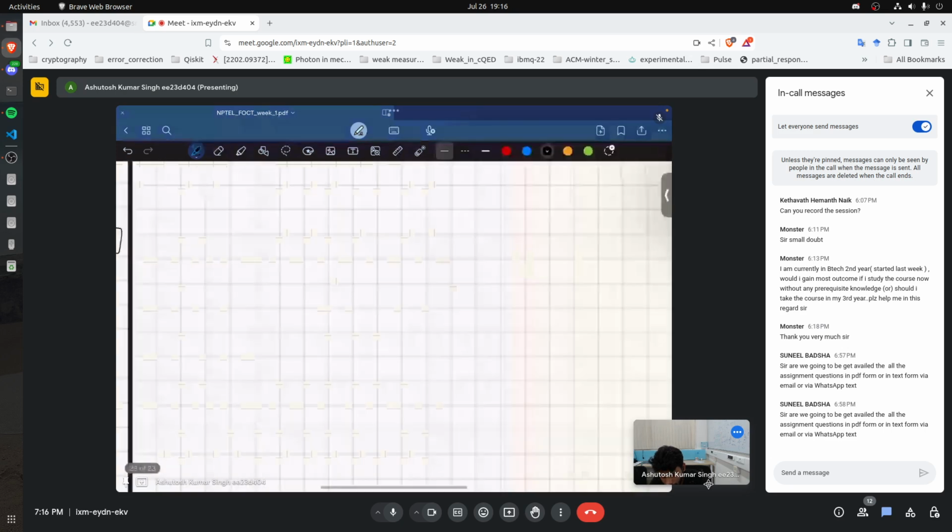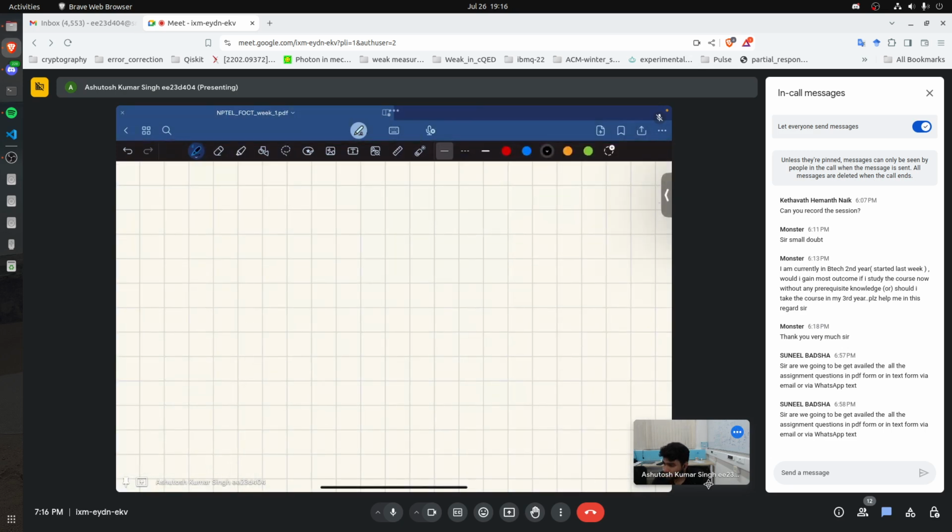Now let us look at the next question. The next question is, what is the modulation format you would pick if you had to transmit 100 Gbps but a symbol rate of 25 gigabaud? I am given a bit rate, 100 Gbps. I am given a baud rate, which is 25 gigabaud. Now this comes down to the same relationship we have been playing with again and again,